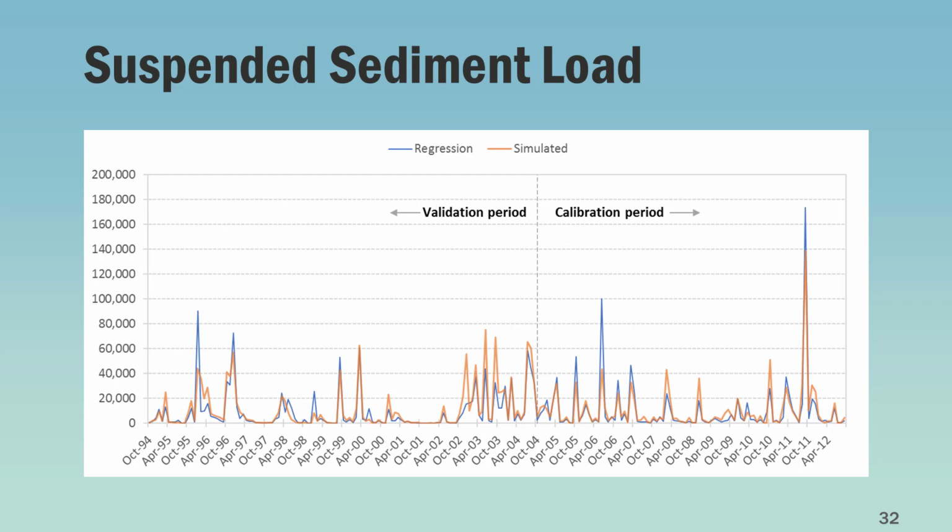A follow-up to my question: it only scours the bed and not the side channels or side banks. So how did you account for that simplification? Again, this is a one-dimensional model, as I had mentioned. Right now, all of the channel loads we are assuming are associated with the bed sediment. So we did not per se account for the bank sources, and that's a limitation of the HSPF model that we recognize. It's again a one-dimensional, completely mixed stream model.